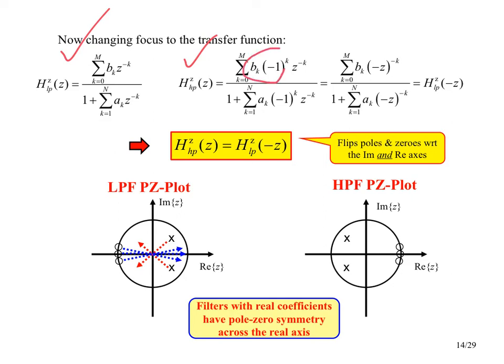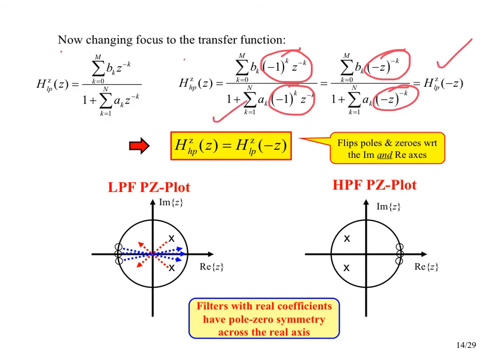We keep this structure, and we're just replacing the exponentials, the e to the j things, by the appropriate z's. And then let me back up a little bit here. Instead of grouping this with the b's and the a's, we're going to group those together, and we see that we get (-z)^(-k) rather than z^(-k). And so we have proved that our result that we puzzled out earlier actually holds from a mathematical point of view as well.